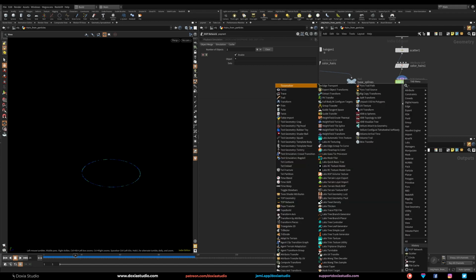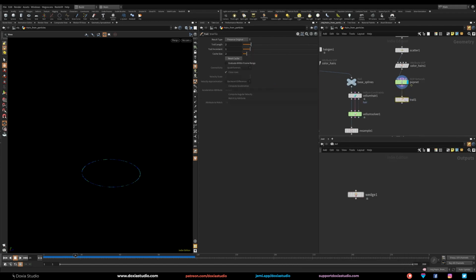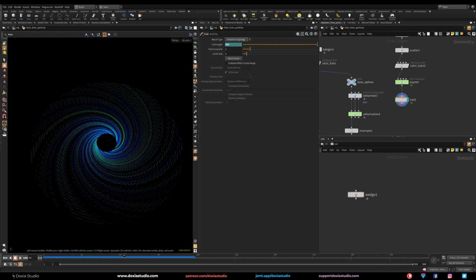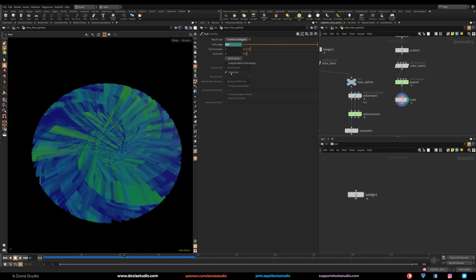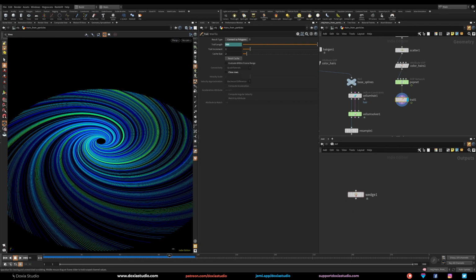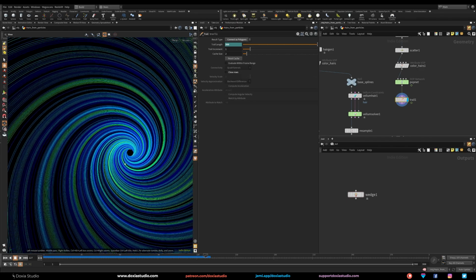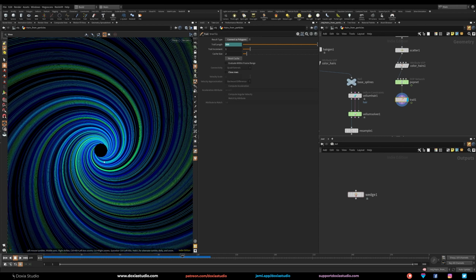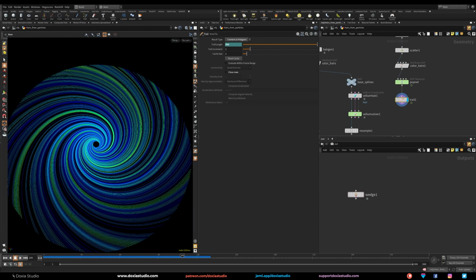And now let's go and create a trail. Okay. And here, let's put the same number as we have on our timeline. Let's go with frame end, so it will pick the 300. Let's go here, and now we have points. Pretty cool. And we can come here and connect as polygons, close rows, and we have our trails. Pretty cool and simple. I think this is a really cool animation. It's just simple vortex.